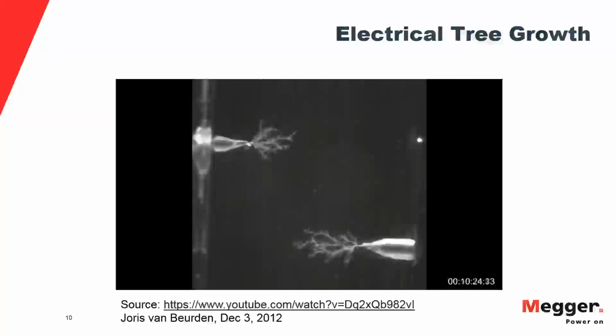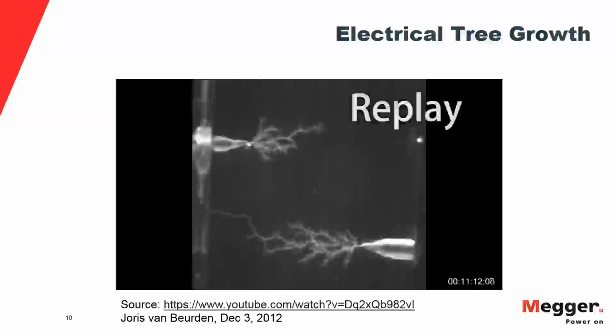If this video would play, there we go. So what we'll see is on the bottom you have minutes, seconds, and frames. So we're already up to about 2 minutes of electrical tree growth. This does take a little bit for the trees to grow, and in this video it's the bottom one that fails, so keep your eye on that. And what you'll see is that the trees start growing and growing, and at some point the bottom one especially will just kind of accelerate to a very quick failure. So it's starting to accelerate now and fails very quickly after that point.